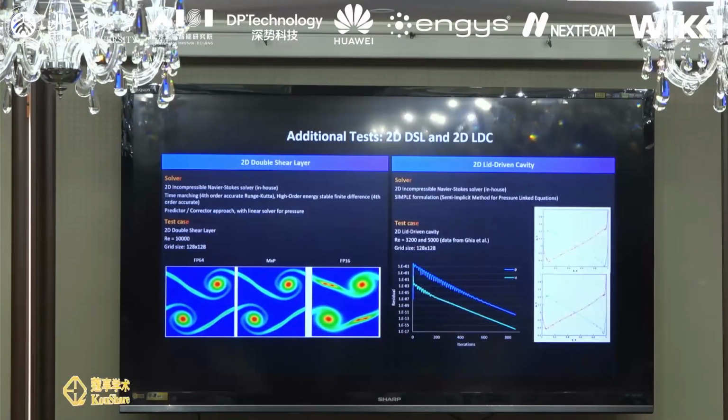And then we also ran the 2D lid-driven cavity. So again, that case is very similar to SimpleFOAM now. We are solving the momentum and the pressure equations one after the other. And what we showed is that we managed with the mixed precision solver to recover the convergence that we would have obtained with FP64. And we also compared the results with experimental data. And that was, at this point, the main aspect of the research: to show we can recover the accuracy.